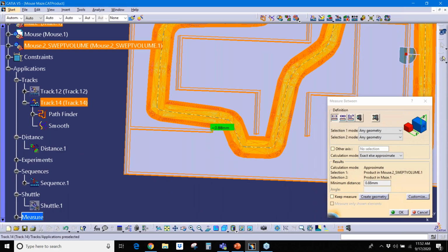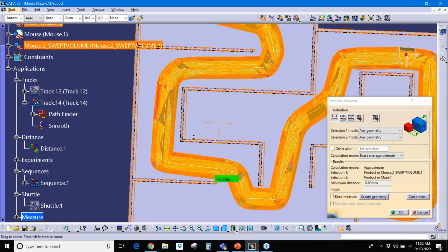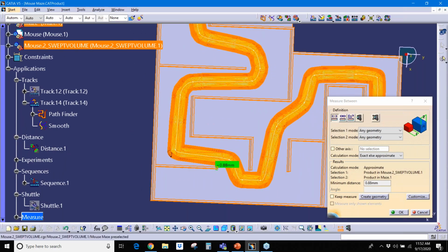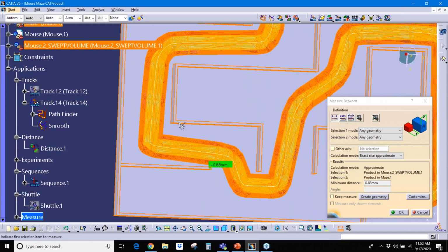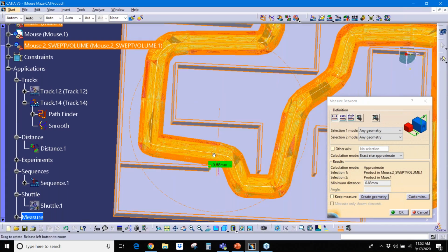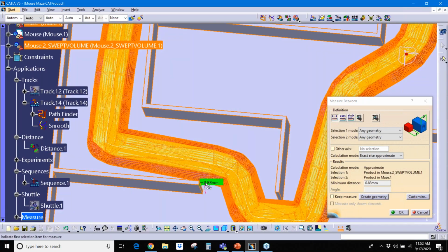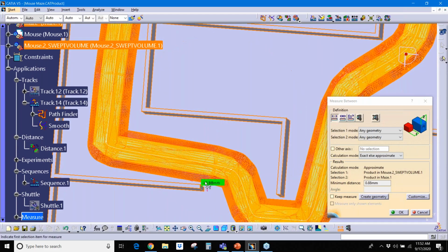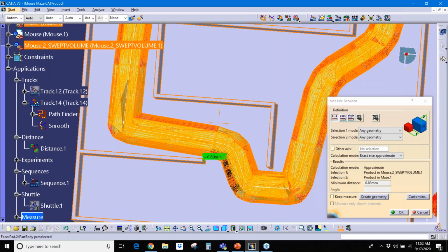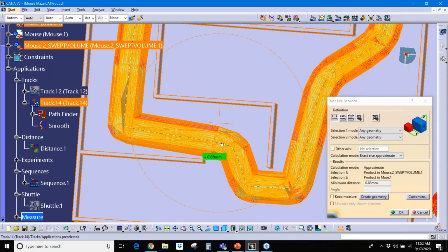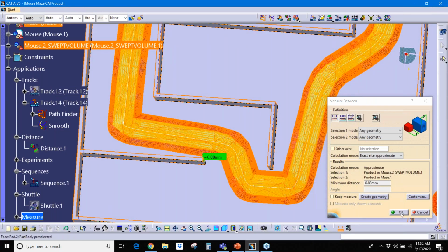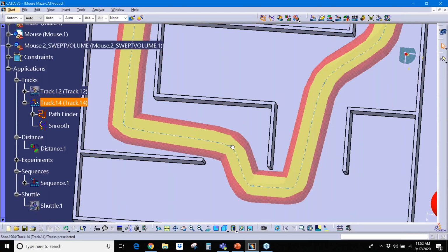And that mistake was, remember this corner, I adjusted that corner to kind of back it away, so that I had that minimum clearance. Well, by adjusting that corner, I kind of modified the spline somewhere else. So now I actually have a minimum clearance distance that's being violated here. You would have discovered that if you reran the experiment, or now you can quickly discover that with the swept volume. And once again, you could come back in here to this location and take this spot and move it up a little bit higher.